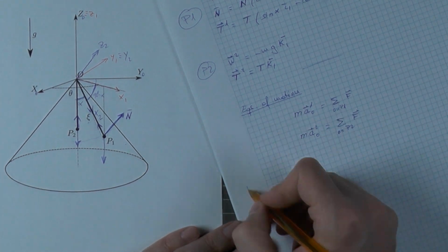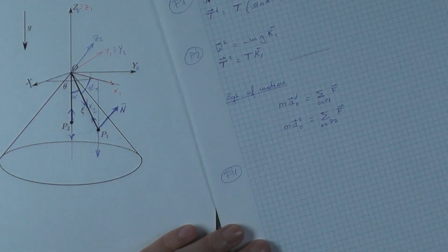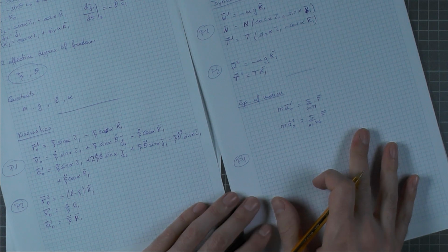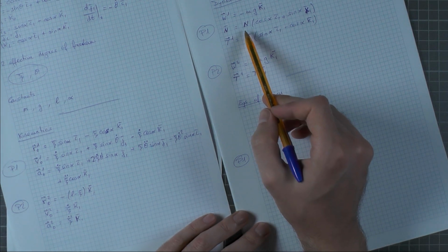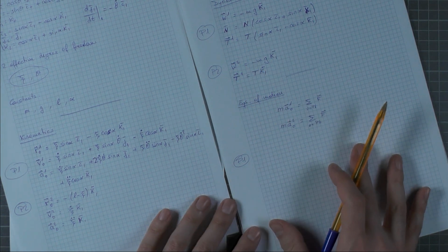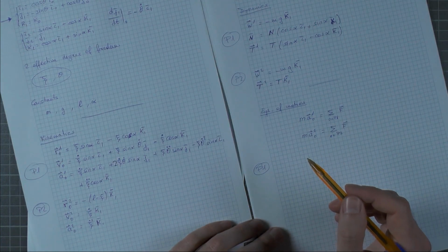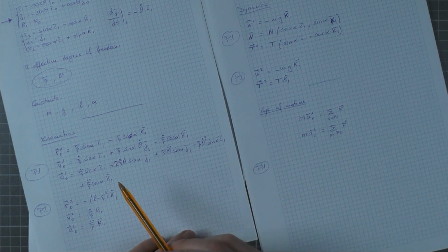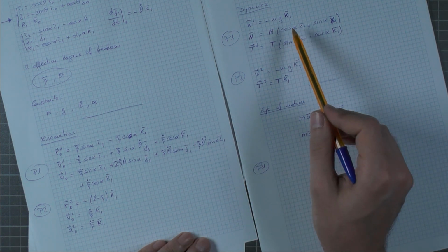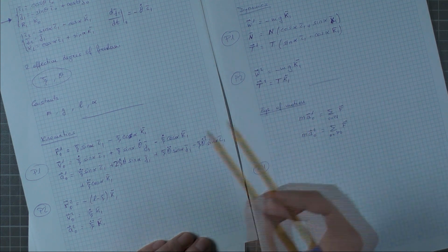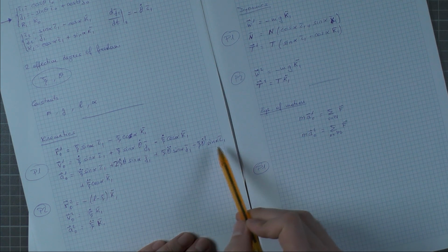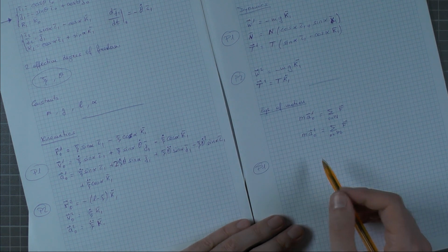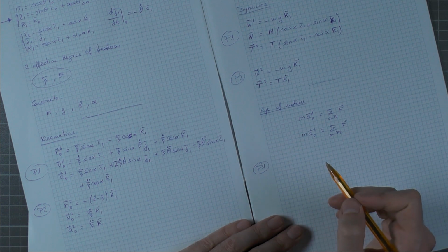So starting with particle 1, we have our acceleration from the kinematics, and we have our forces over here. We only need to choose in which three directions to project this vector equation. Since I have already written down the acceleration and the forces using the basis B1, I1, J1, and K1, I'm going to use these same three directions to project the vector equation to obtain the three scalar equations.